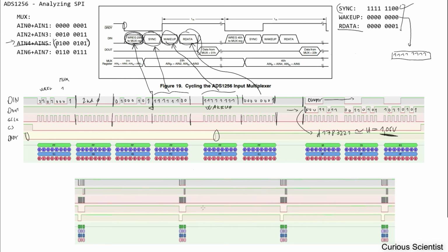And what I have down here is just, as you can see, the same data sequence over and over again. What we can do here is just measure this time, for example, or between the data ready, it doesn't really matter, and measure the time or the frequency, and this is 825 Hertz.